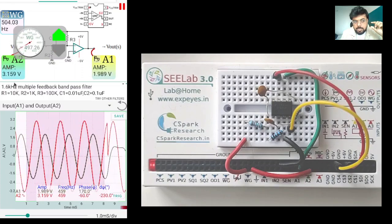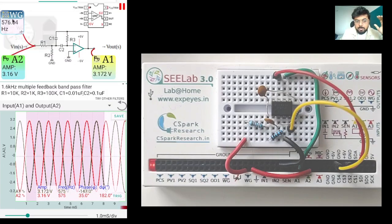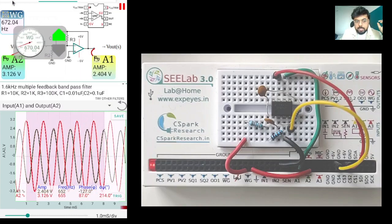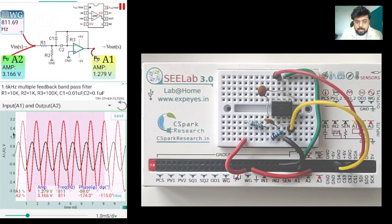Now, as you keep increasing the frequency, at around 600 Hertz, both have the same amplitude, right? Let's keep increasing it. You see, beyond 600, it's reducing again, which tells us that the peak of this bandpass filter lies somewhere around 600 Hertz. Now, coming back to this amplitude here, let's extract it from the graph.